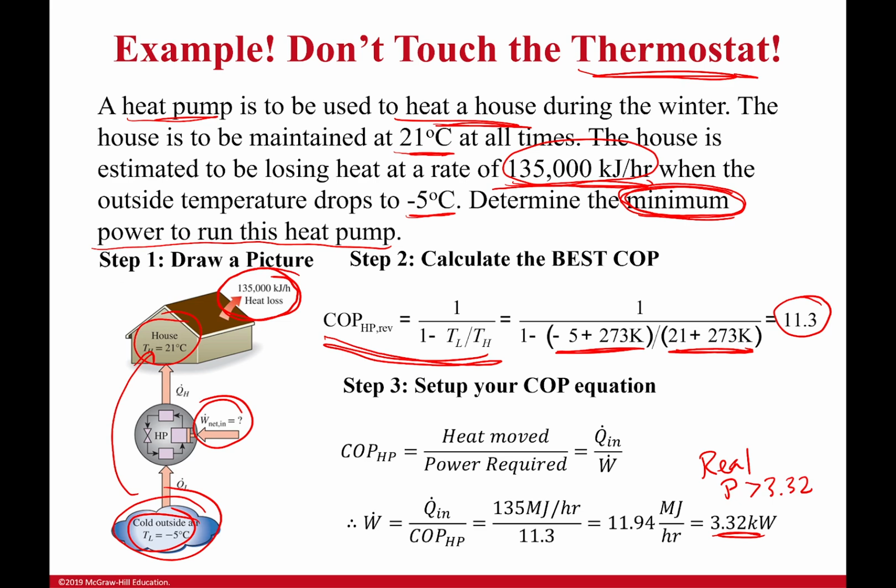Well, it's not all that crazy. If you want to reduce your electricity costs when it comes to heating, number one, you can reduce the temperature in your house. If I go down to 19 degrees Celsius, my performance will increase. Also, the amount of energy I'm losing from heat loss will decrease too, because it's based on the temperature differential.